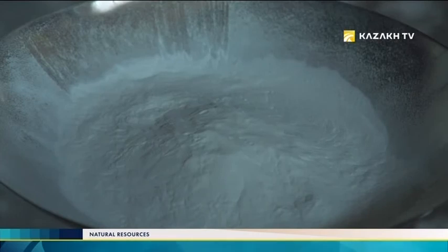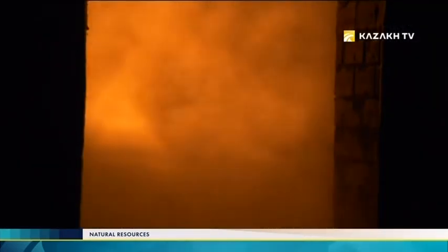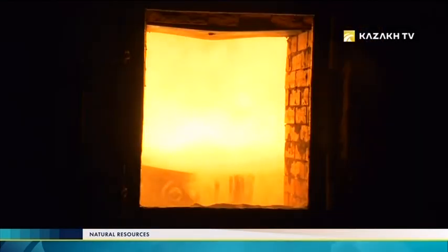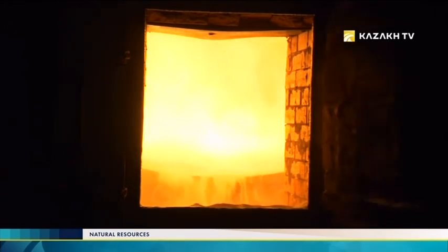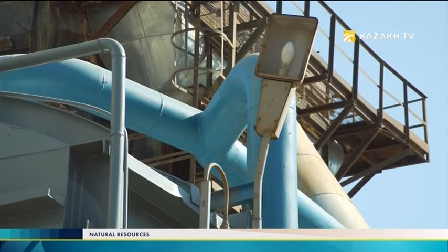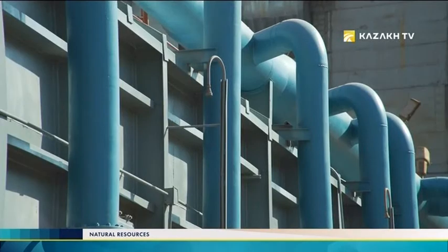The third section is ignition section, which is located in the zone of burning torch, which provides the highest temperature of gases, 1400 Celsius degrees. Thus the burden can be heated up to 1250 Celsius degrees. And these very parameters provide modification of alumina from one state to another. Cooling section is the final stage of the calcination. Here the final alumina will be cooled down till 1000 degrees.